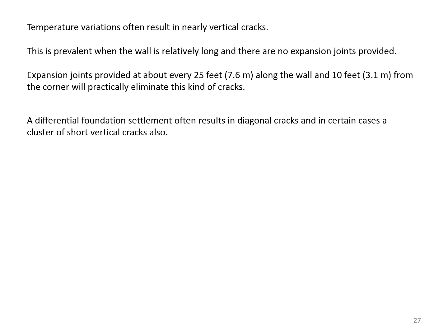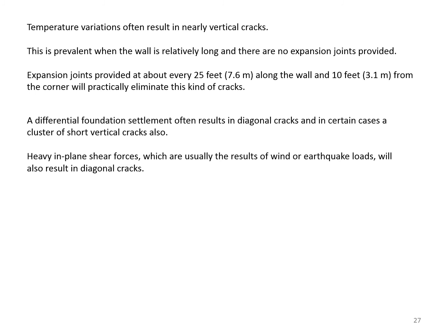A differential foundation settlement often results in diagonal cracks and in certain cases a cluster of short vertical cracks as well. Heavy in-plane shear forces, which are usually the results of wind or earthquake loads, will also result in diagonal cracks.